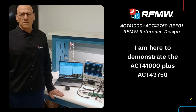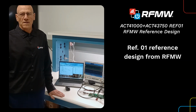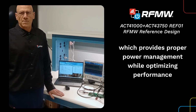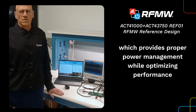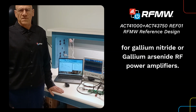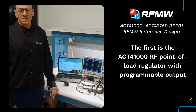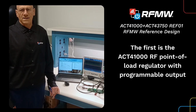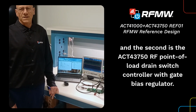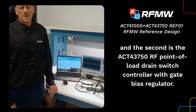I am here to demonstrate the ACT41000 plus ACT43750 REV01 reference design from RFMW, which provides proper power management while optimizing performance for gallium nitride or gallium arsenide RF power amplifiers. The design features two Qorvo devices. The first is the ACT41000 RF point-of-load regulator with programmable output, and the second is the ACT43750 RF point-of-load drain switch controller with gate bias regulator.